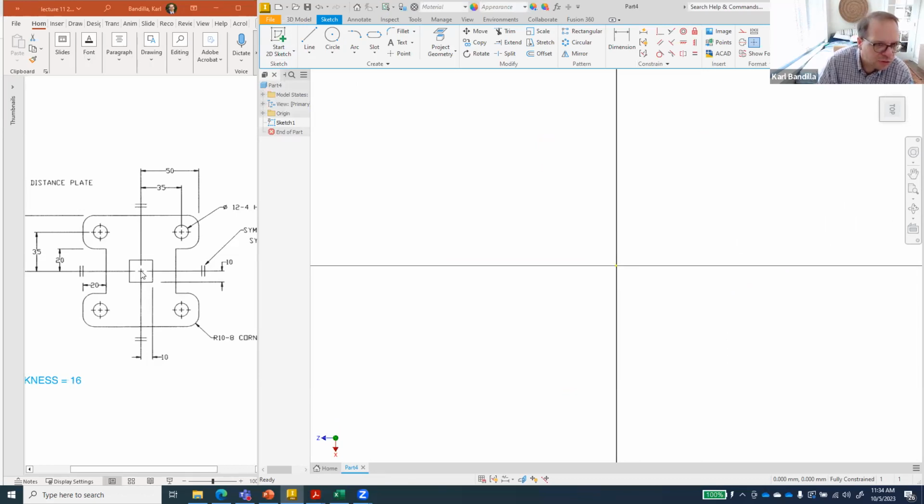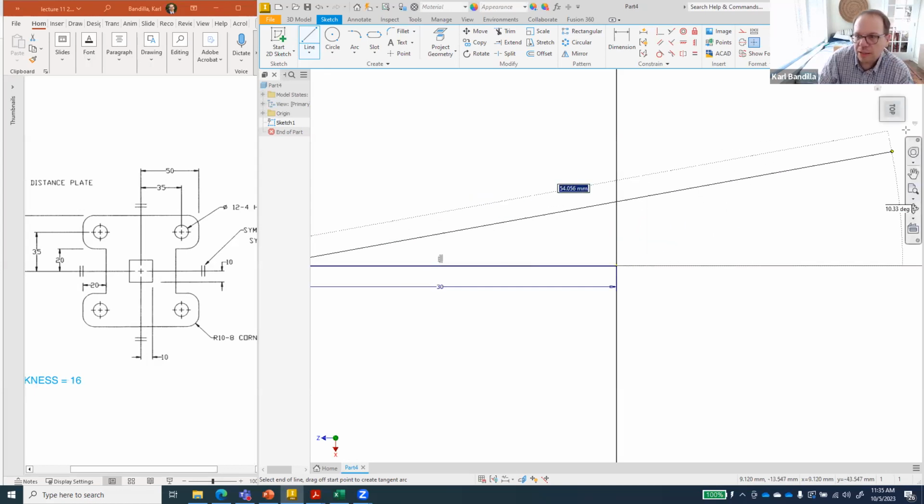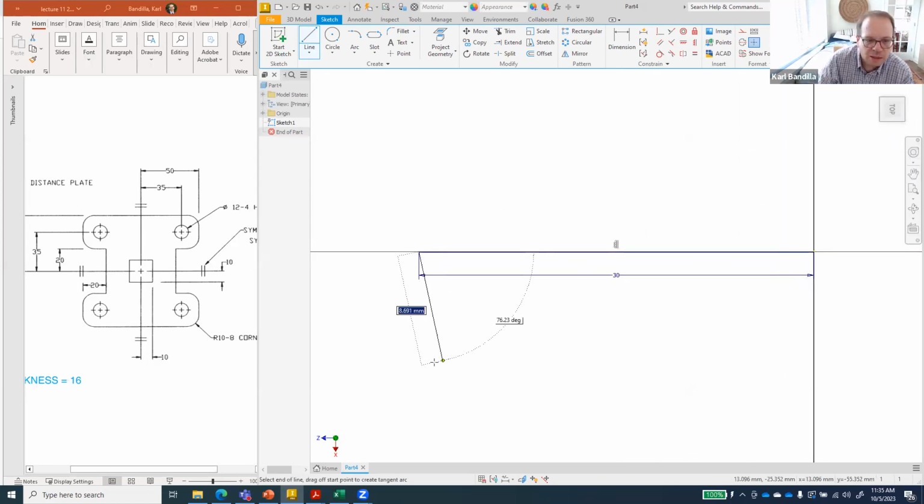It makes it easy for us to draw. So let's draw a line that we can throw away later. But we know from the center out to here would have to be how far? All the way out is 50, it says there. And it says that from here to here is 20, and it's all symmetric. So that's 50 minus 20 is 30. So let's draw a line that's 30 right there. Then we want to go up 20.